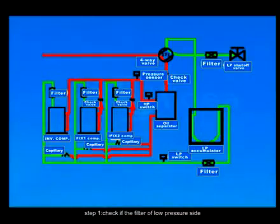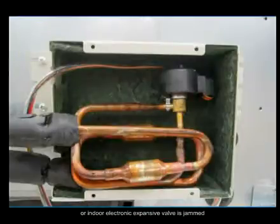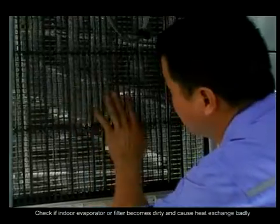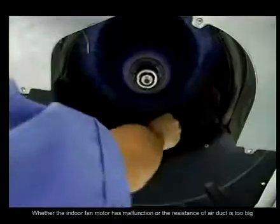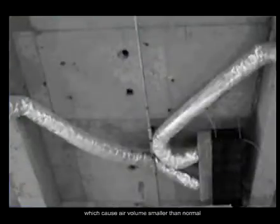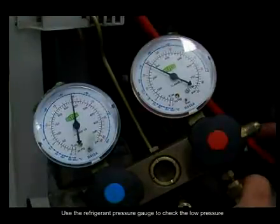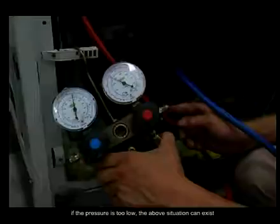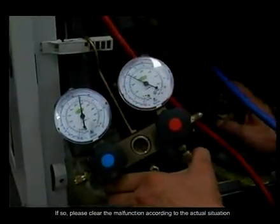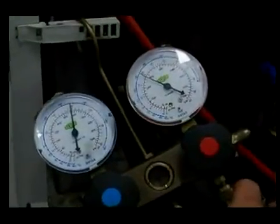Step 1. Check if the filter of low pressure side or indoor electronic expansion valve is jammed. Check if indoor evaporator or filter becomes dirty and cause heat exchange badly. Whether the indoor fan motor has malfunction or the resistance of air duct is too big, which cause air volume smaller than normal. Use the refrigerant pressure gauge to check the low pressure. If the pressure is too low, the above situation can exist. If so, please clear the malfunction according to the actual situation. If not, please go to next step.